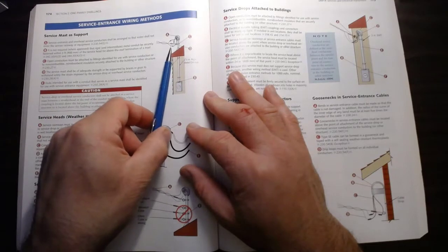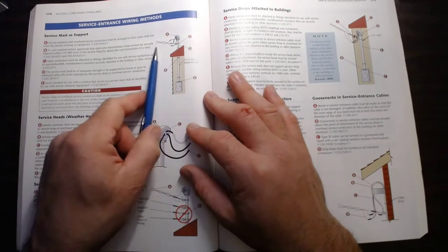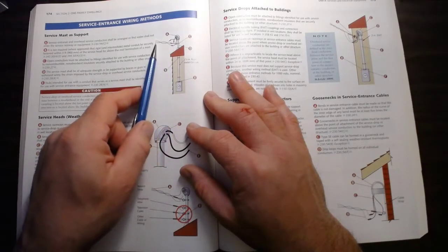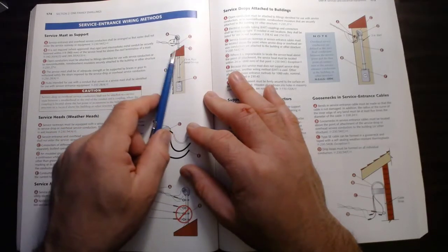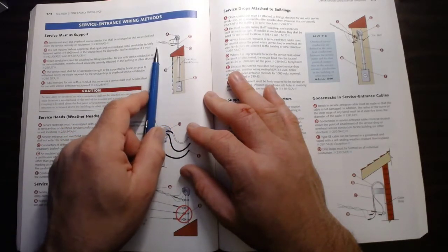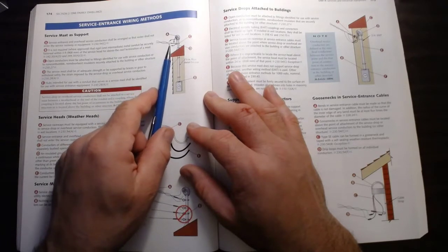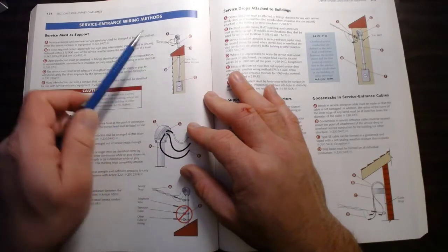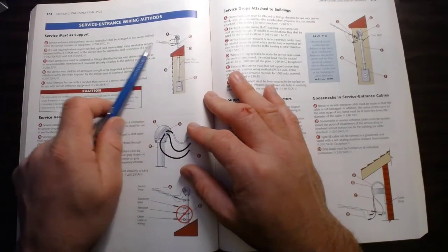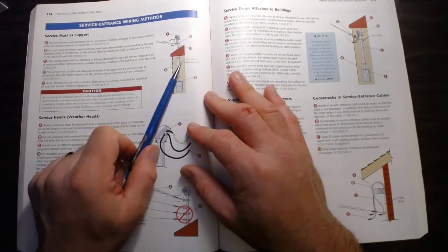So you've got to think about the weight of this triplex overhead conductor, which is primarily used now. And triplex is a bare steel neutral, and then an insulated two hots. So the supporting wire, the guy wire, is the neutral, and then the two insulated are wrapped around. We call that triplex, 3 wires wrapped together. There's a considerable weight to that depending on the distance it has to go.